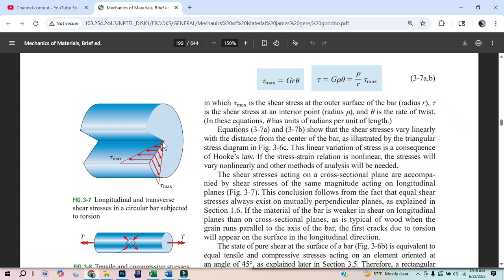And this is the same longitudinal. So this is where you have to understand that, hey, for steel, your material's homogeneous. It doesn't really matter. It has an equal opportunity to rip apart in rings, or rip apart in tension, or longitudinally. So just the fact that you have little squares that you're ripping apart, one down, one up. In that process, don't think of it that way, take this little square, and you're actually ripping that square this way and that way. So those two things are happening.